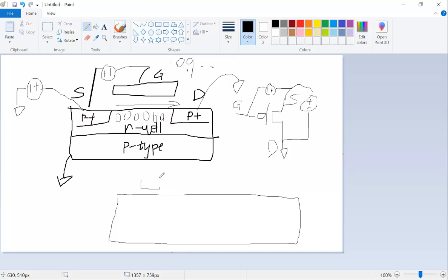You got one transistor here, which is NMOS, right? You don't need to do anything. You don't have to put in the N-well because it's already N+. It doesn't make sense to put it in the N-well. So the N+ is in the P type substrate. So the P-type, the wafer itself, is the body of it.